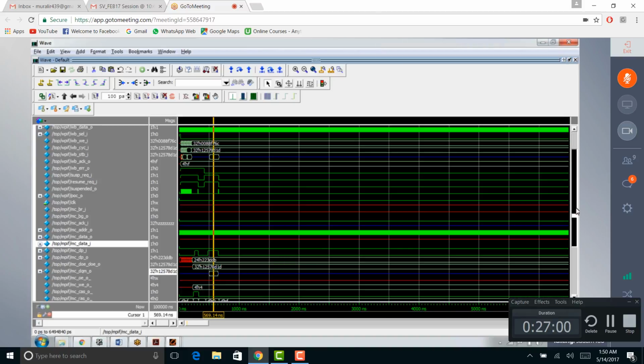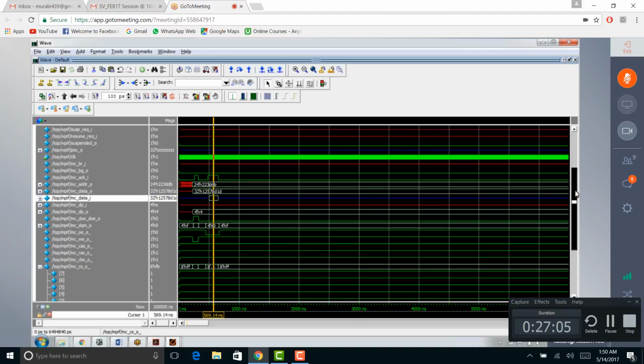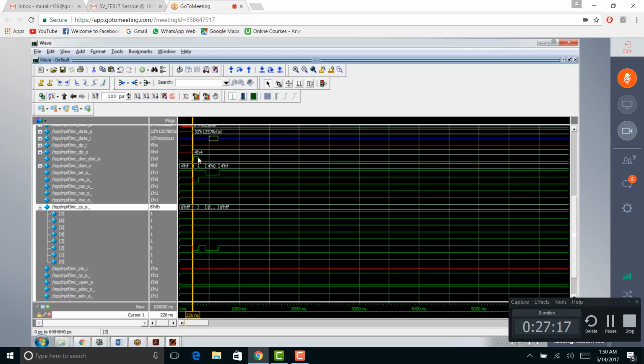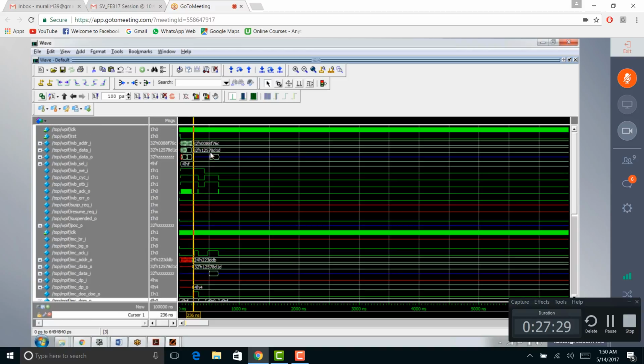Now which one is it happening on really? If you check chip select, you will come to know where it is happening. It is happening on chip select 2. On chip select 2, whichever memory is connected, the synchronous chip select device connected, there it is happening. You can see the value you wrote here, 12578D1B. That is the data you wrote. You are reading the same data, you can confirm here, 12578D1B.